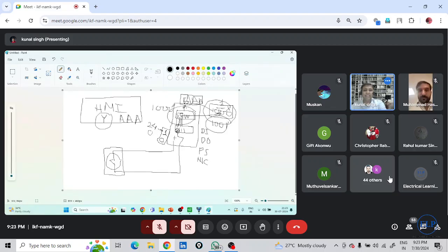So I wired this to 1000, and then I connected this to AAA. So first this is coming to 1000, then going to AAA. So the HMI will come to know that this breaker is in on condition, and it will change the graphic in its monitor.